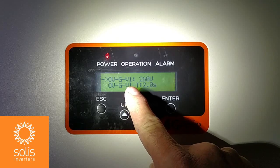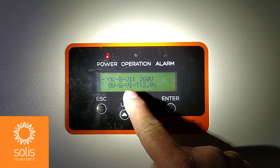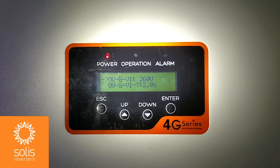And when we see a 2 there, that means we are adjusting our absolute trip time and trip limit. So here we are for our overvoltage of the grid, our intermediate trip limit of 260. We may find that some particular site is running a little high on voltage, and so we may want to increase that a little bit.